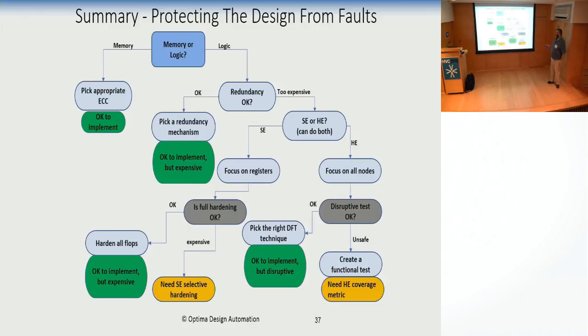If disruptive test is okay, you can go to the DFT people in your design and ask them for the best system they have with the right parameters and runtime and cost and so on and memory. But this becomes a manufacturing test problem, pretty much solved in the manufacturing world. You can negotiate with the DFT team and get the right answer. It's okay to implement, but it's disruptive. Remember, you said it's okay to take the part offline every millisecond. If it's not okay, then you need to create a functional test. And if you're doing a functional test, you need to understand the coverage metric for it.